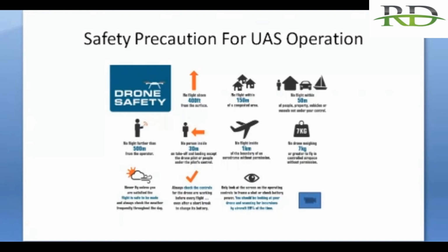Also, there should be no magnetic or electronic fencing, high-power electronics, big generators, or wind formations causing restriction. Weather is also very important: the condition of the air, air movement, cloudy weather or sunny weather, is important when using the drone in a particular area.